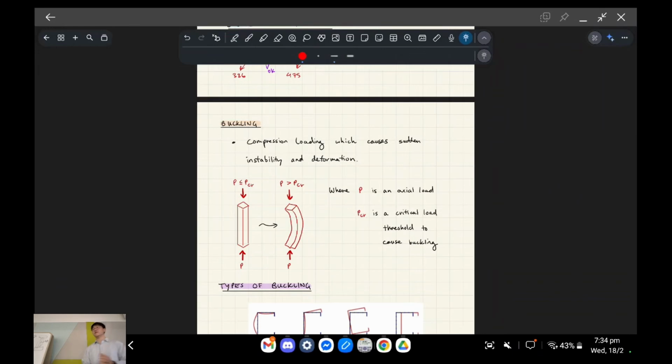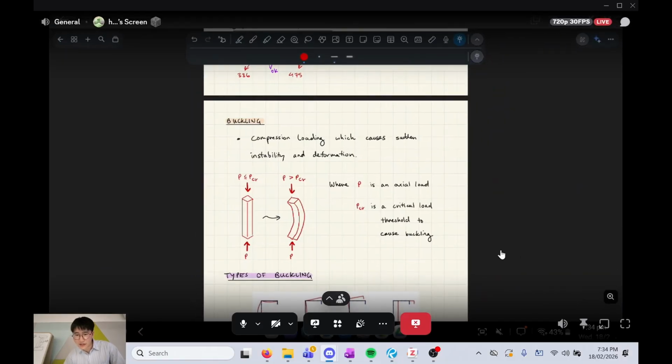But for steel, a big part of the design of steel is managing the slenderness of it and managing essentially buckling. That's what I want to leave you guys on in terms of what to look out for in this course. That's definitely the hardest concept to grasp in terms of the numbers and all the theory. But if you understand it, you should accept it. Okay, so that's all from me. I'll shut up now, and yeah, thank you.